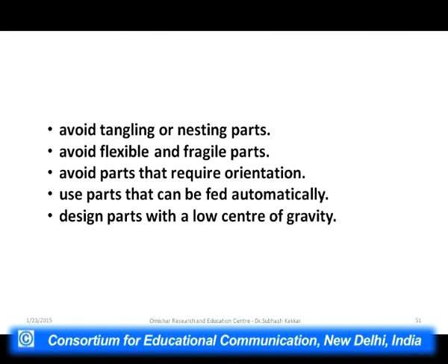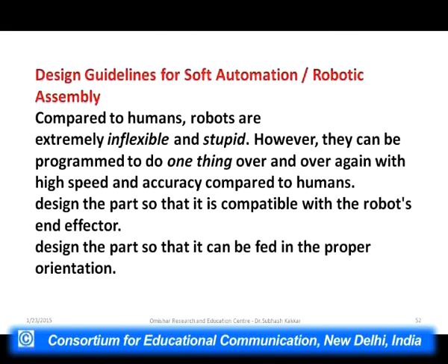Avoid tangling or nesting parts. Avoid flexible and fragile parts. Avoid parts that require orientation. Orientation-free parts should be used. Use parts that can be fed automatically, and design parts with a low center of gravity. There should not be any question of parts falling down.